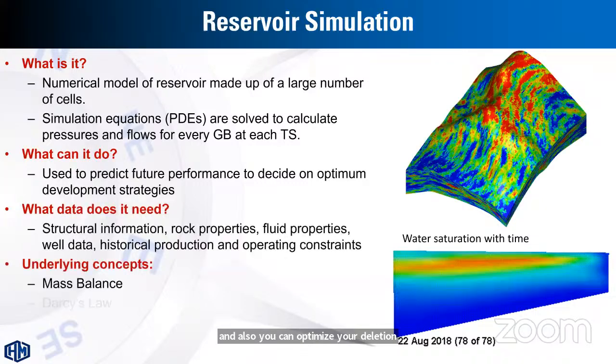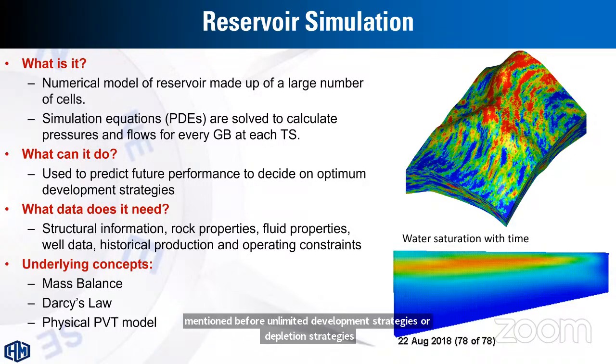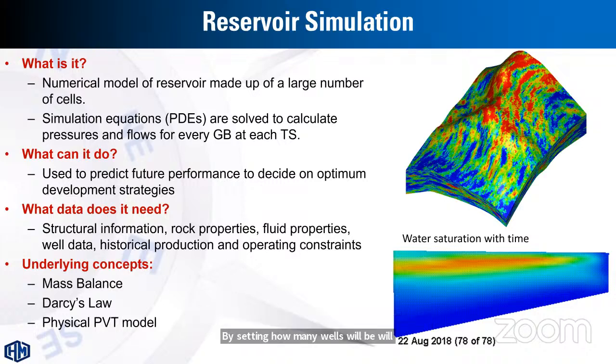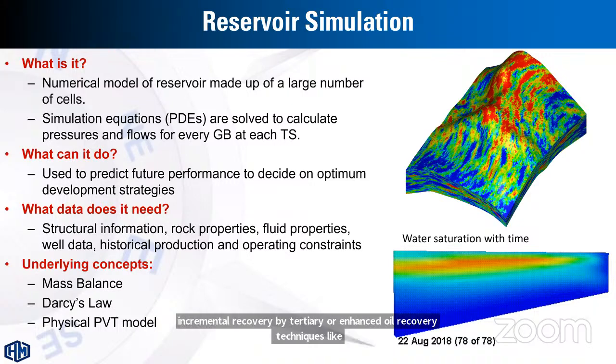So we need this approach to predict the field performance under unlimited, as mentioned before, unlimited development strategies or depletion strategies, by setting how many wells will be drilled, what the secondary recovery technique is, which one is better, water injection or gas injection, and the pilot or testing of the incremental recovery by tertiary or enhanced oil recovery techniques like surfactant flooding, or even polymer flooding, and so on.